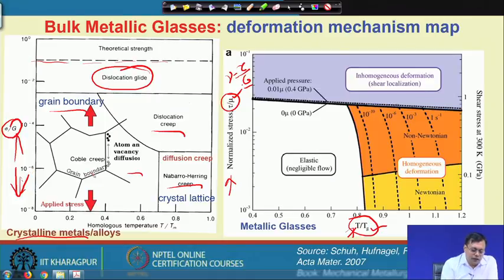So, this is known as a Coble creep, which is also a low temperature creep process, and grain boundary is more activated in this particular process, because for atomic diffusion to occur through grain boundary does not require very high temperature, where the bulk diffusion or crystal lattice diffusion relatively requires a higher activation energy.